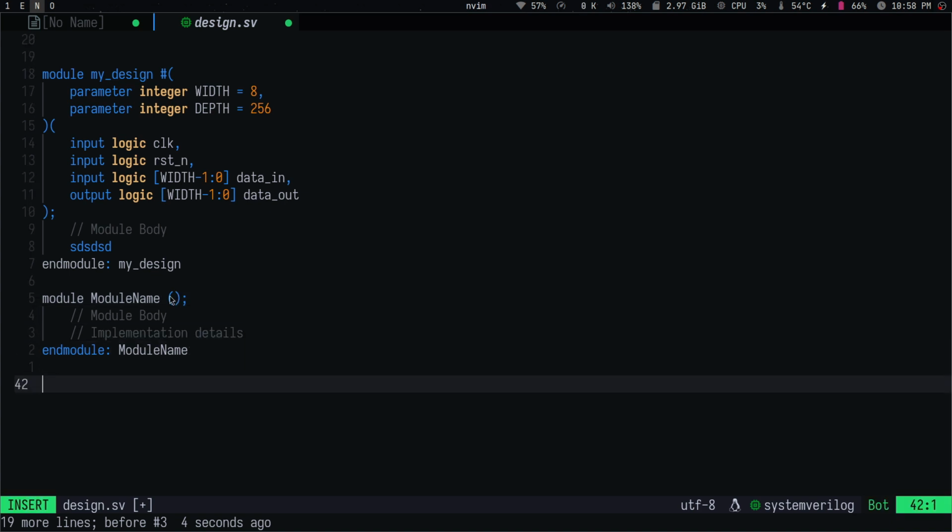So you might be asking, why didn't I remove this part? Because SystemVerilog requires, whether it has ports or no ports, to always have brackets. So anyway, just between the two. Now the nice thing about all of this is that the generation of this one and the generation of this one is done with only a single snippet, a single trigger that I have to remember. So I just have to remember module.